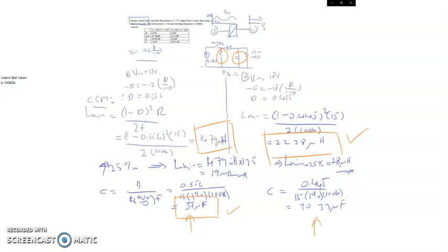because this will support the 12 volt operating condition as well. So 22.28, we move to the next highest value of 23 microhenry. It does not have to be exactly 22.28, but around 23 microhenry is sufficient for our system. So 23 microhenry for the inductor, and 37 microfarad may not be available in the market, so we can select 40 microfarad, which is the next highest available in the catalog. Okay, that's all for question number 7.